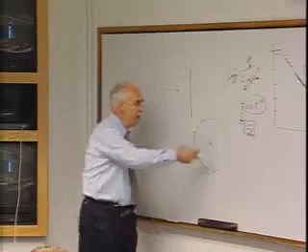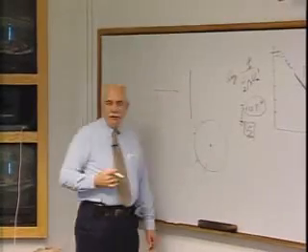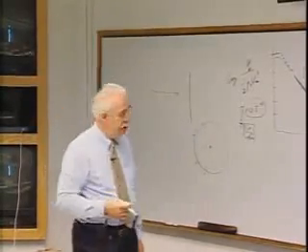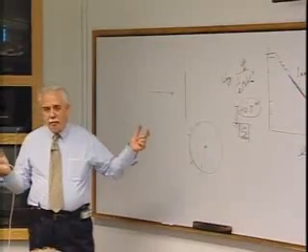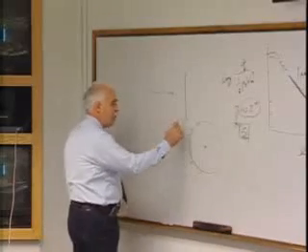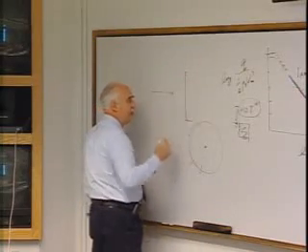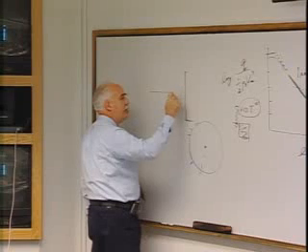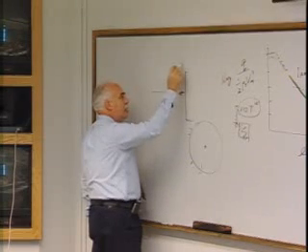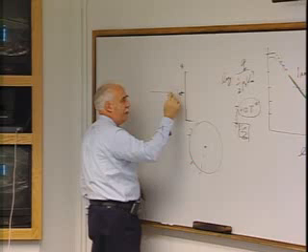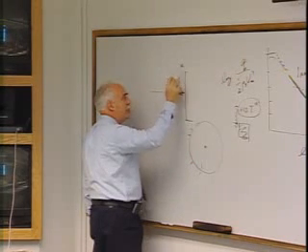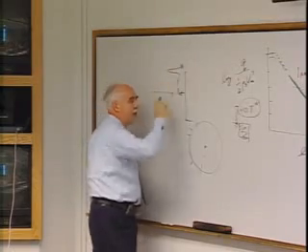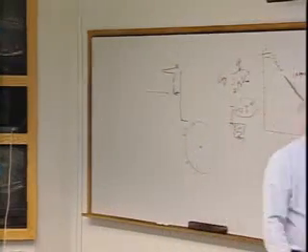Well, that'd be great. I could spin it and distribute the heating over the entire thing as I enter. That happens to some meteors. Well, it's not too comfortable, and I don't have control, and I also generate a little lift. There's all kinds of problems with that. One other problem, if I use just a section of a flat plate, if I look at the heating distribution, if I plot the heat transfer in this direction from ground test, and also not from flight, from ground test, you have some level of heating, but then when you get to the corner, it really goes up because of the pressure gradient, the same thing that we experienced on Apollo in terms of the ablator.